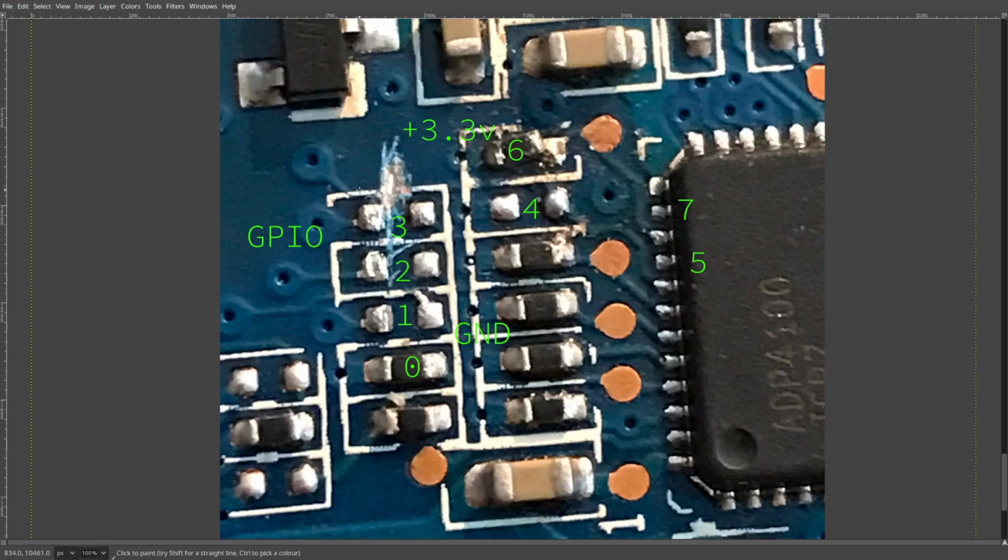Also, you'll notice here, this is where your GPIO pin connections are. So basically, VID 3 goes into this via, VID 2 goes into that via, VID 1 goes into this via. Don't worry about this via, that's something else. And then VID 4 kind of continues along here and goes into this via. So to basically disconnect this, these are really easy. You just desolder your resistors. These vias are all ground, so let's look at, for instance, VID 0.